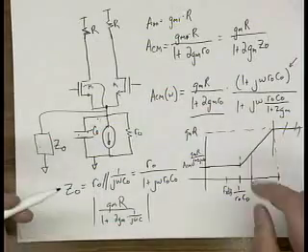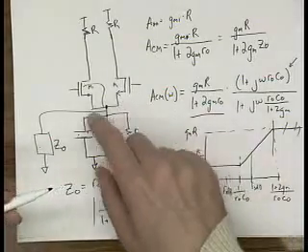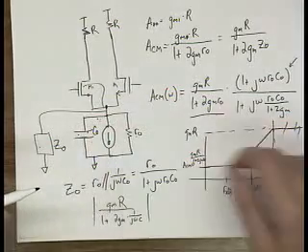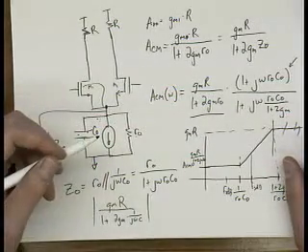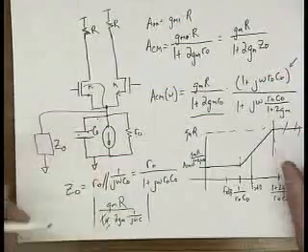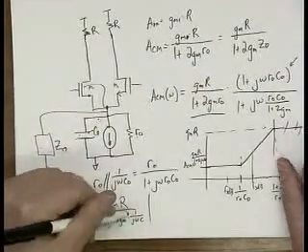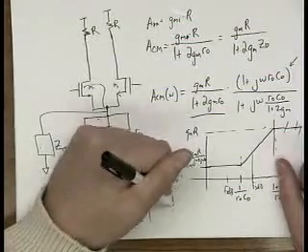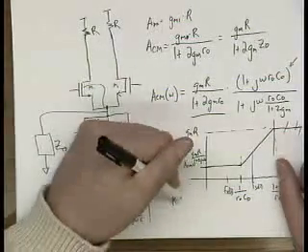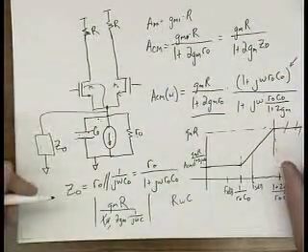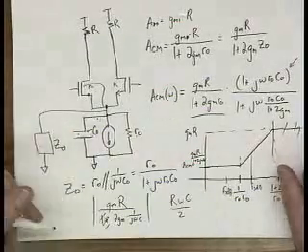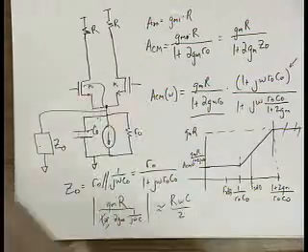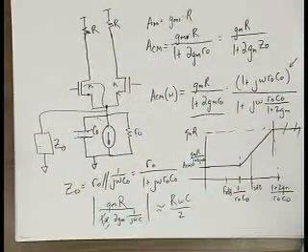Beyond this frequency, the degenerating impedance is that capacitor, so chances are that'll be small. It'll basically be R load times ωC over 2, roughly. And you just need to calculate whether that will meet spec when you cascade in everything else you've done.